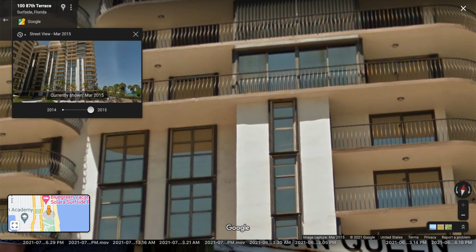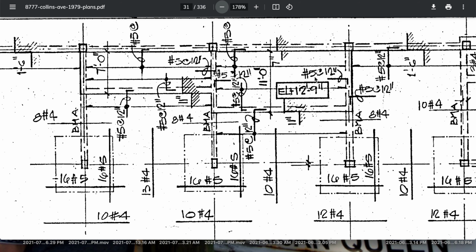A transfer beam, so imagine this is the floor. You can come out to the deck, all the way up. But to avoid an overhang, you put a beam across these columns from here to here, and now you can load your floors all the way up. So there's the transfer beam. This beam goes from there, and now you can have your loads across it.